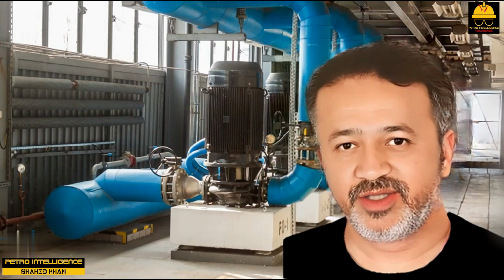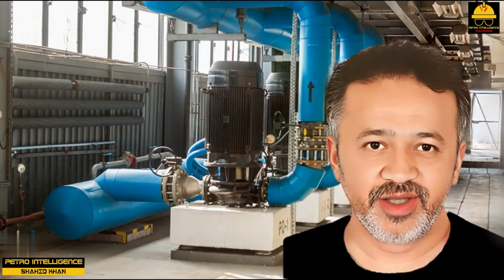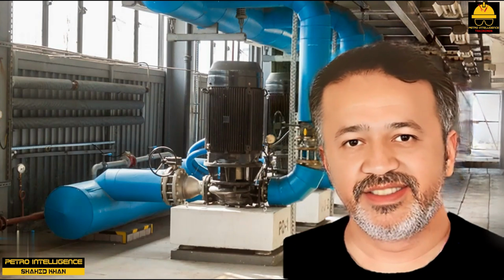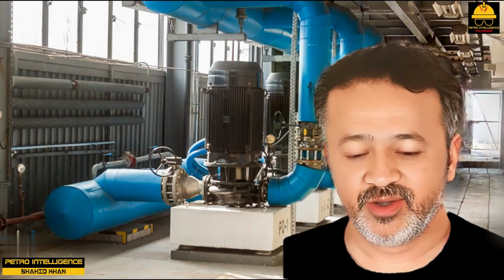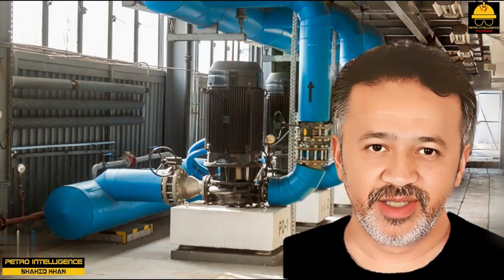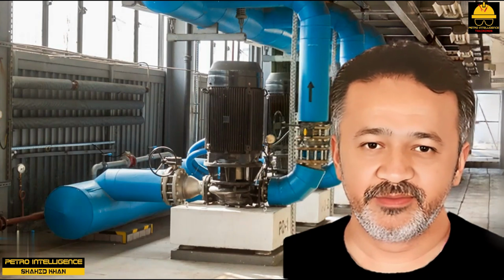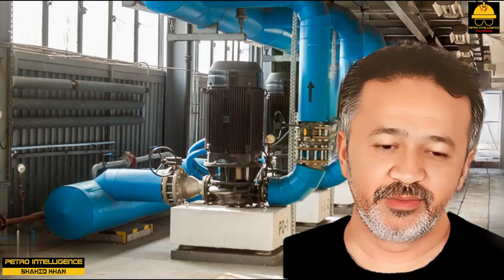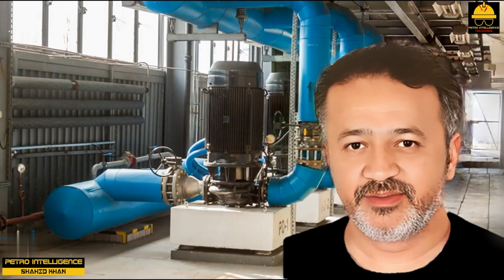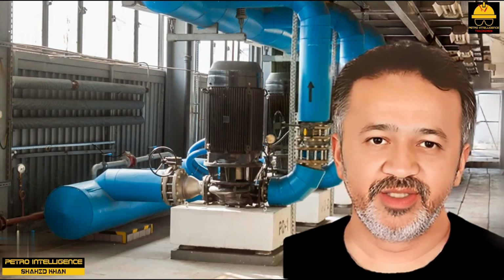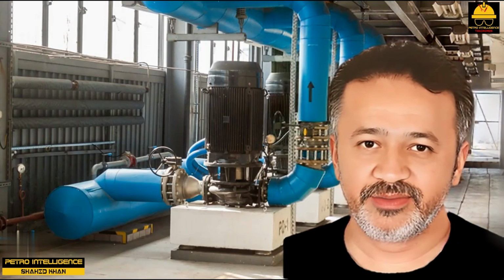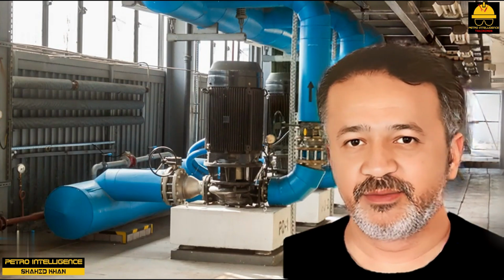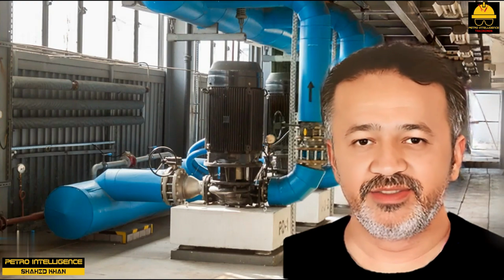Last question: water is being pumped to a tank on a hill at 100 GPM. If we now switch to pumping a lighter fluid at the same rate, can we pump the lighter fluid to a higher elevation, only to a lower elevation, or the same elevation? Answer: the same elevation. Centrifugal pumps develop the same feet of head at a given volumetric flow rate regardless of the specific gravity of the liquid pumped. This means the ability of the pump to push liquid uphill is the same even if the density of the liquid changes.